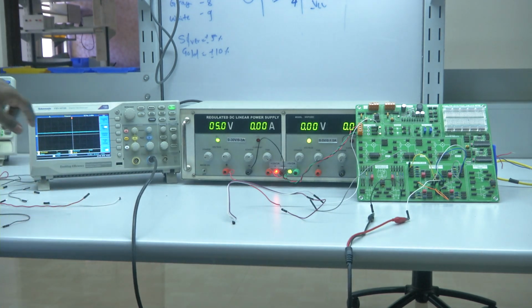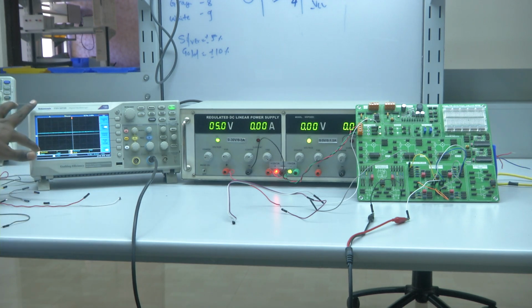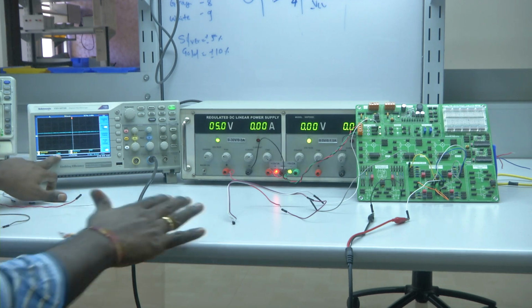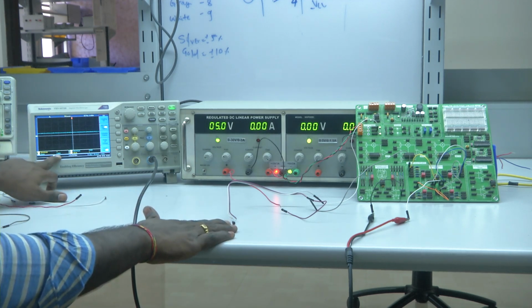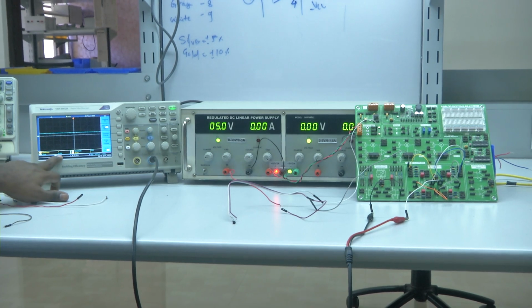Now when we look into the oscilloscope, here we can see that the mean value is 2.87 volts. If you recall the complete working of the system, we know that the gain of the system is 10, and by looking at the output voltage we can understand, since it is not connected to any plant right now, that it is at room temperature. The room temperature is around 28.1 degrees centigrade.